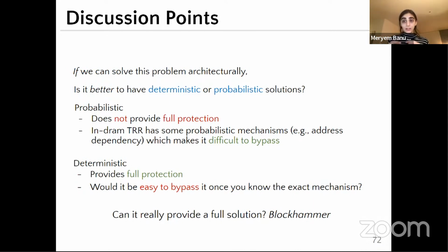But it doesn't necessarily change the number of bit flips you have in this specific victim row, right? And I think the ECC is capable of only limiting a couple of bits per cache line. I cannot see how we can really decrease the number of bit flips we have in a victim row, because I think we either protect the victim row or not protect the victim row, but maybe my intuition is not correct. What do you think?